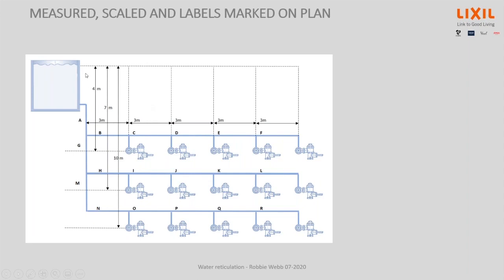Okay, so remember that a standard FLUSHMASTER needs only 30 kPa, but it's got a peak flow of 105 liters per minute, which means it needs volume. So that's why it's got that almighty big 1.25 inch inlet. Okay, so this information on the primary criteria table we're going to get.